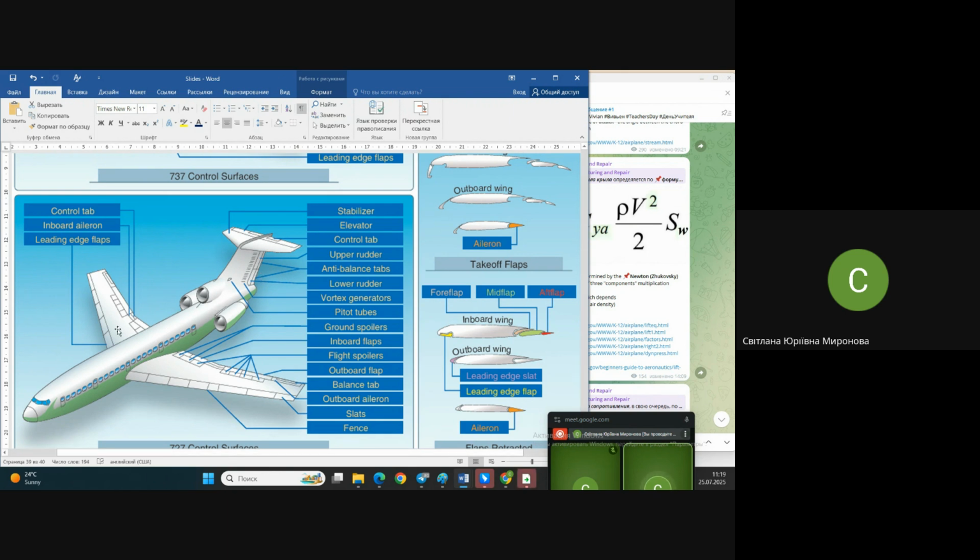And the same on the wing. They have flaps. The simplest to find are the ailerons, always at the end of the wing. It's not true, because next we will talk about hybrid surfaces, hybrid flight controls. You will be surprised that maybe it's not quite true that they are always at the end.